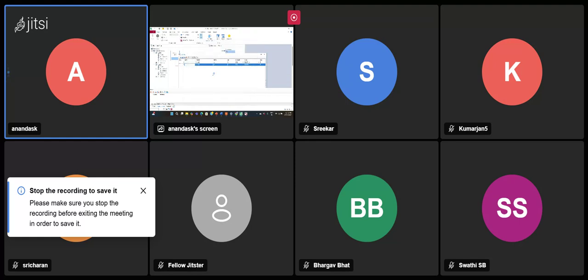So why do we use this IG block? I think everyone knows it in automotive, but in our project we are not using this IG block much. But this is one feature where, without stopping our CANoe simulation, we can send some messages periodically or manually.